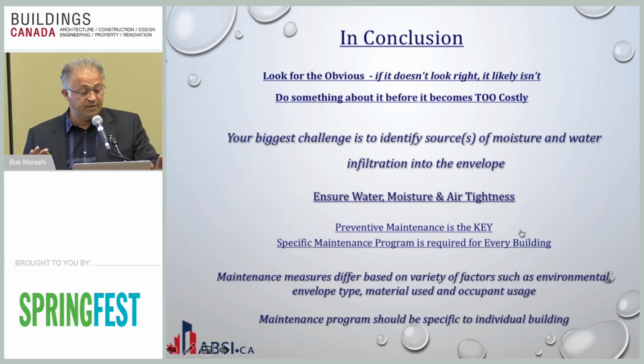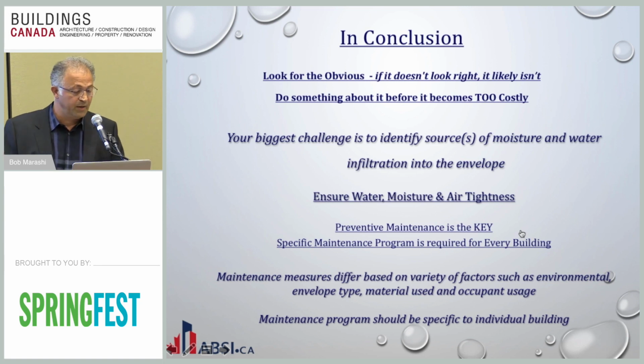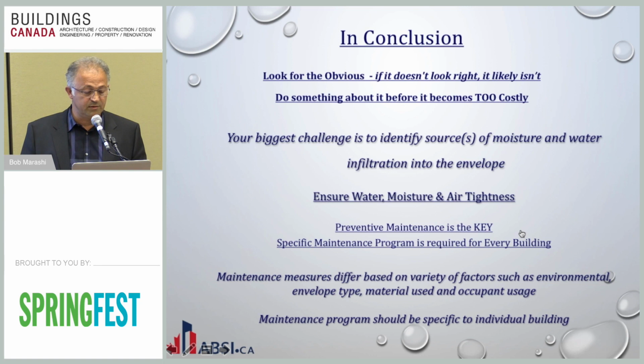Maintenance measures differ based on a variety of factors, such as the environment that the building is in, envelope types that the building has, or material and occupant use. You have to apply different maintenance methods for different buildings, for different locations, for different usage. You can't just say, I'm going to do tuck pointing repair on this building and I'm going to do that for all my buildings. Well, if the other buildings are different types, you can't do that. If they're in different locations, they need different times, different life cycle to carry out these repairs.